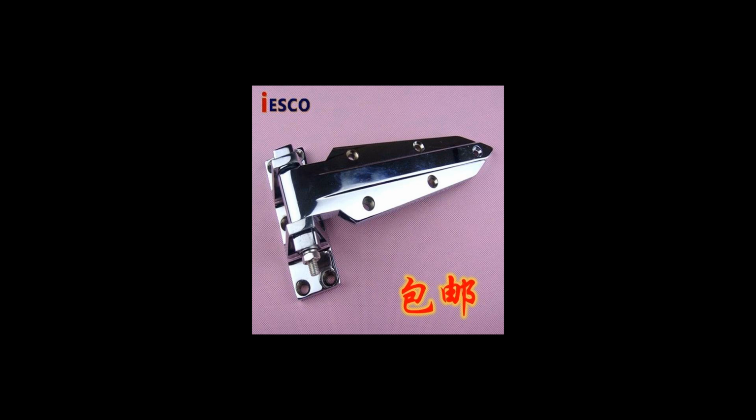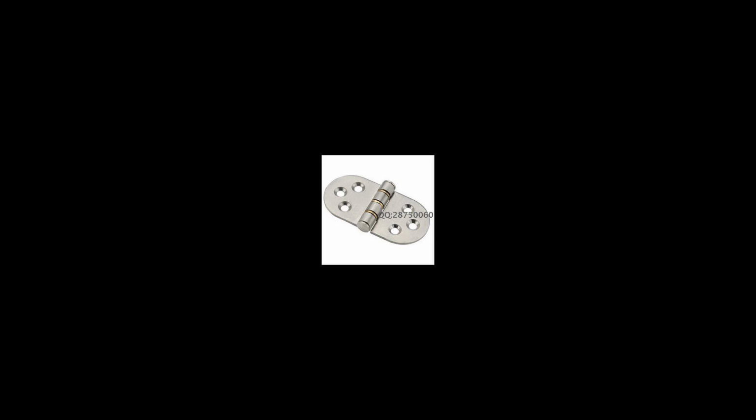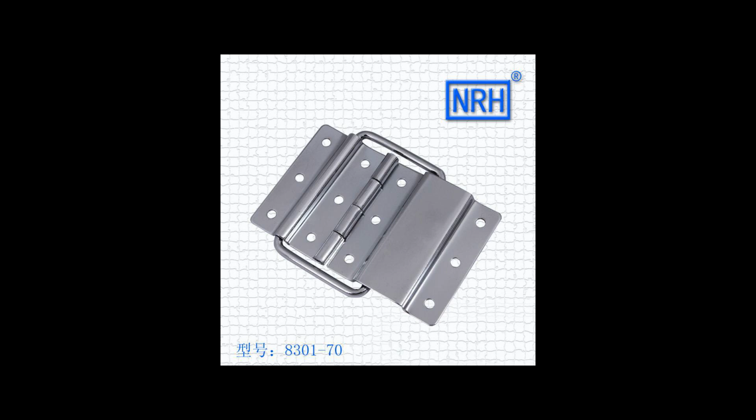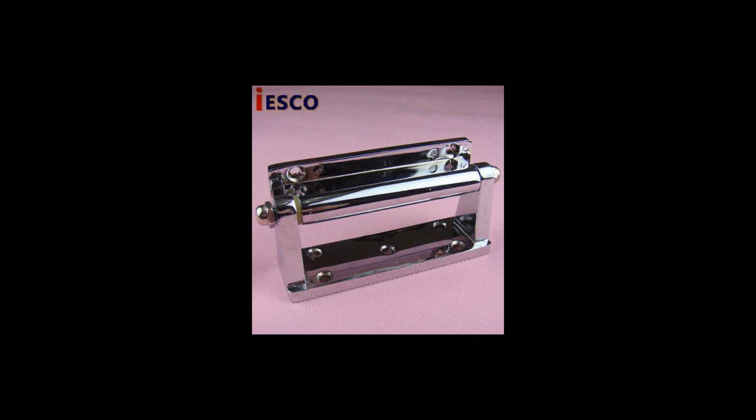Butt mortise hinges, usually in 3s or 4s, which are inset, mortised, into the door and frame. Most residential hinges found in the US are made of steel, although mortise hinges for exterior doors are often made of brass or stainless steel to prevent corrosion. Case hinges. Case hinges are similar to a butt hinge, however are usually more of a decorative nature, most commonly used in suitcases, briefcases and the like.